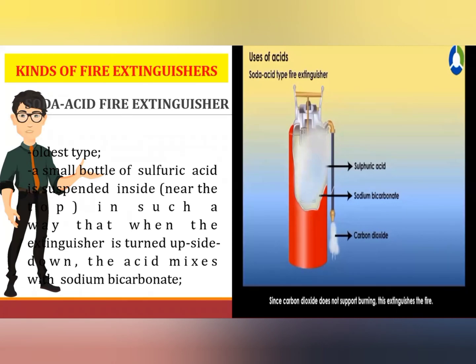The working principle of any fire extinguisher is based on the following conditions: cooling the combustible material below its ignition temperature, cutting off the air supply, or both simultaneously. There is a solution of sodium bicarbonate in water in the fire extinguisher and sulfuric acid in a different bottle within it. The sulfuric acid combines with the sodium bicarbonate solution and creates carbon dioxide gas when the fire extinguisher is operated by turning the knob on it.